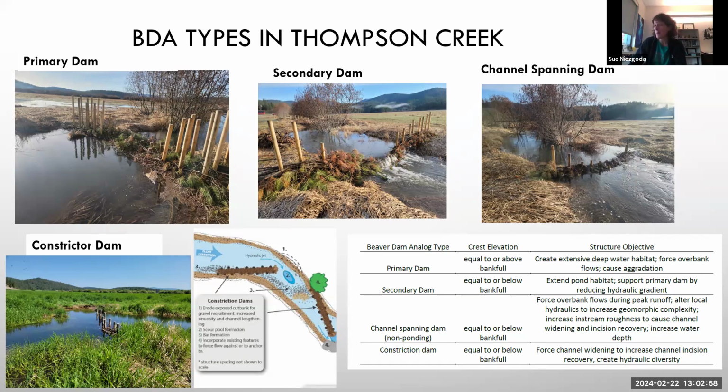So to actually come up with our overall complex design here, I used what's known as a relative elevation model, which looks at high points and low points from LiDAR data of the river and the floodplain. I was also trying to look at where old relic side channels might have been that you can't really see on the ground when it's all covered in vegetation, but the LiDAR data can show you that, and you can highlight it by color coding it based on elevation.